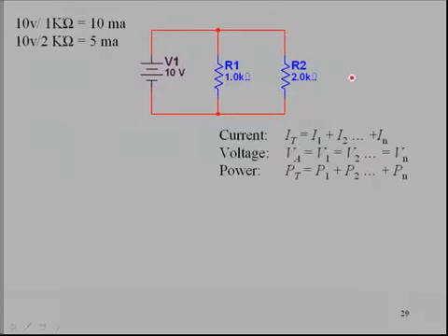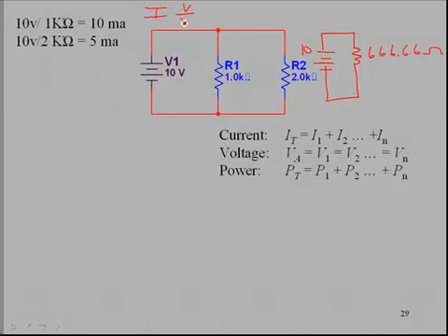We calculated the total resistance. Why don't we throw that in here again, and I'll quickly draw this in. We said our total resistance was 666.66 ohms, and our applied voltage, again, 10 volts. That's the equivalent resistance. Now, for the current, remember, current equals voltage divided by resistance. And so here we have an applied voltage across this component.